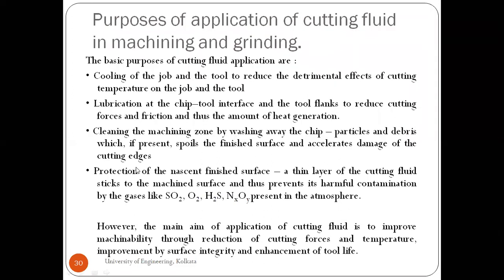So the purpose of application of the cutting fluid in machining and grinding is cooling the job and the tool to reduce the detrimental effects of the cutting temperature on the job and the tool; lubrication at the chip tool interface and the tool flanks to reduce the cutting forces and the friction, thus the amount of heat generation; cleaning the machining zone by washing the chip away, right? Particles or debris, if present, spoil the finished surface and accelerate the damage of the cutting edges. And finally, the protection of the nascent finished surface.